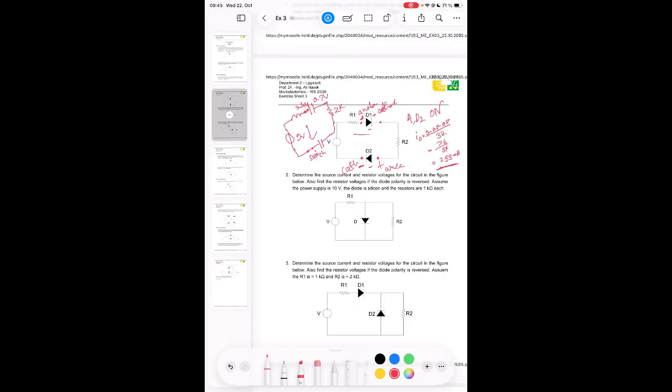Usually, it depends also on the question you have. For example, the diodes are silicon. This information is only important if you are not taking ideal, right? So if you decide to take voltage drop model, it's fine, you can take 0.7. If you decide to take the piecewise model, you will recognize, okay, I still have a missing information, so I'm going to take the voltage option. But still, I'm definitely going to try to just say, take this one and use this one. Good.